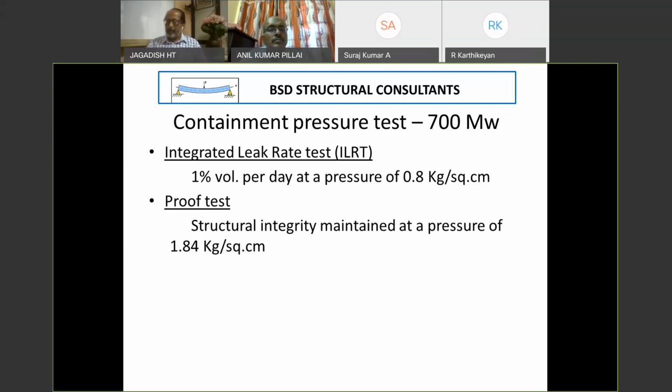Now, coming back to the coolant getting drained out, the loss of coolant which is coming out from the pipe will certainly be highly active water. There's a lot of radiation in this water. Secondly, the pressure inside the containment starts increasing because this water is under pressure. Why does the pressure come? Let me go back to my earlier slides. I told that water as a coolant enters into the reactor and takes away the heat. If you heat water, how much temperature can it take? It can go to 100 degrees centigrade. After 100, it becomes steam. But taking out just 100 degrees centigrade from the reactor is not going to be of help to us at all.